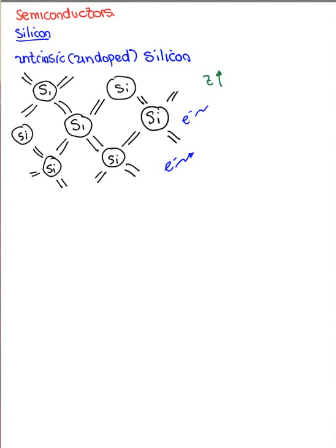And where are these carriers coming from? Well, in reality, once you start putting some heat into the system, then you start bumping some of these electrons out of the outer shells of the silicon atoms, and so they come out, and what you end up with here is a free electron that is moving around in a random manner, and then you have a hole, which is the hole that was left by that electron getting out of that shell, right?